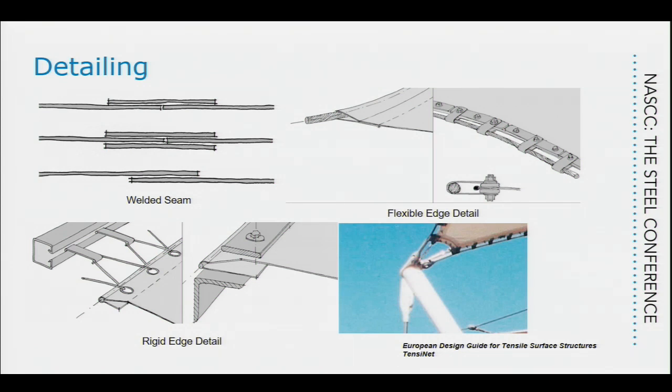But if the strength we need is a lot, or if we're worried that this pocket is going to tear, then we use a detail like what they did here, where we clamp two pieces of steel and pull on that steel so that we don't tear the material. That's a photo of what this one would look like.